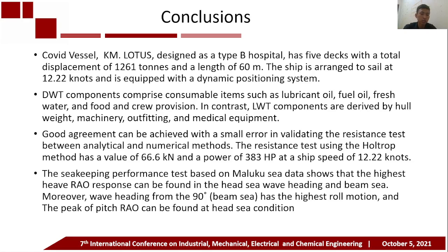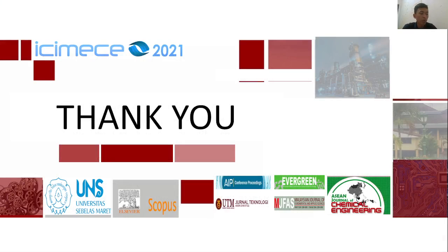Then the last conclusion is that the seakeeping performance test based on Maluku Sea data shows the highest heave RAO can be found in the head sea. Moreover, a heading of 90 degrees has the highest roll motion and the peak of pitch RAO can be found in the head sea condition. I hope my session was valuable and will encourage future research about hospital vessels, especially for Indonesia's remote islands.